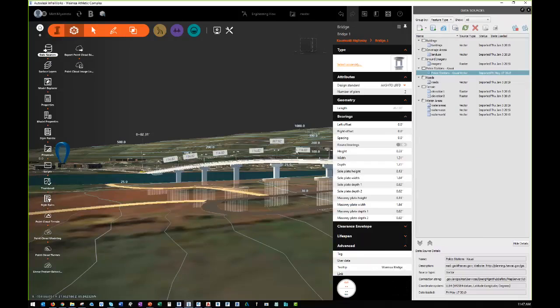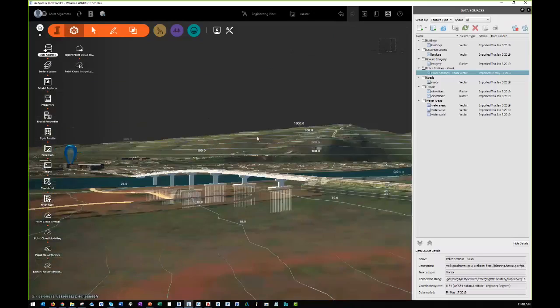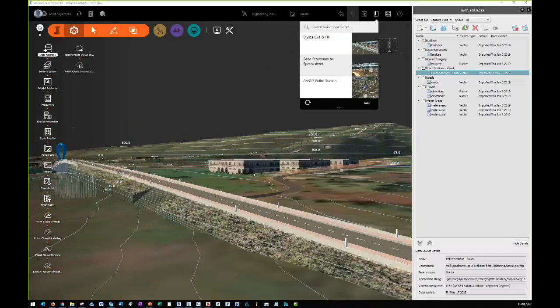then updated again. You are not limited to just simple text like tooltips and tags and data. You can actually change the geometry as well by modifying everything in that spreadsheet. And of course, that was a simple right-click to export, creating a new Excel file, and then once that Excel file is changed, you're going to do another right-click to update the model from there. So we have that edit structures in spreadsheet, and now update the structures from those edits available to you as well.